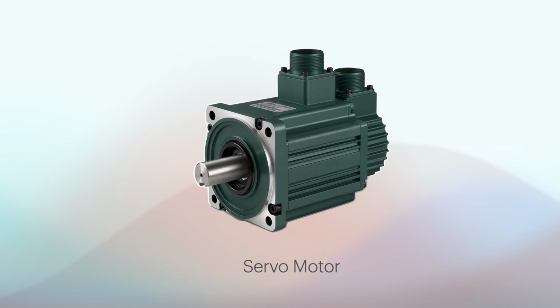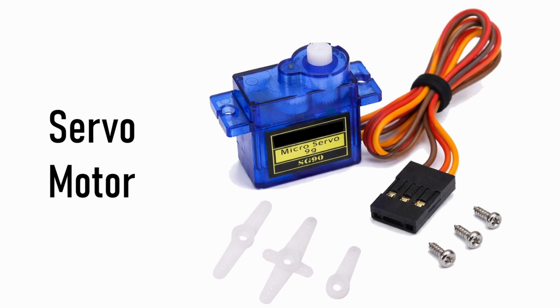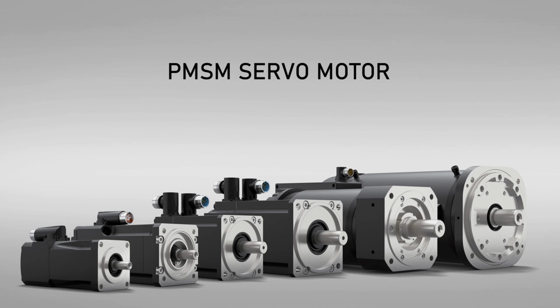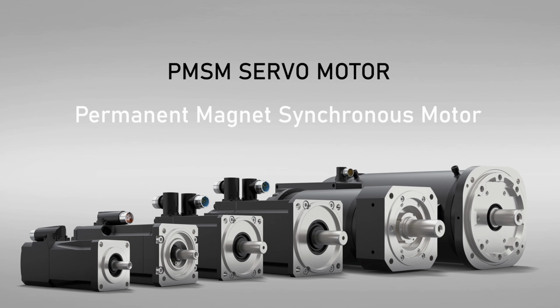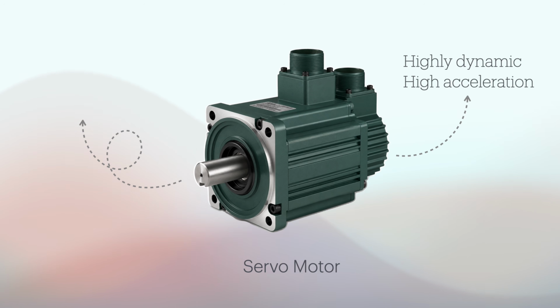Technically, a servo system simply means a device that operates with closed loop feedback control. Therefore, this DIY brush DC motor is also a servo motor. But here we are specifically talking about the industrial PMSM servo motor, permanent magnet synchronous motor. These motors are designed for highly dynamic response, high acceleration, and very precise motion control. This is why they are widely used in factory automation.